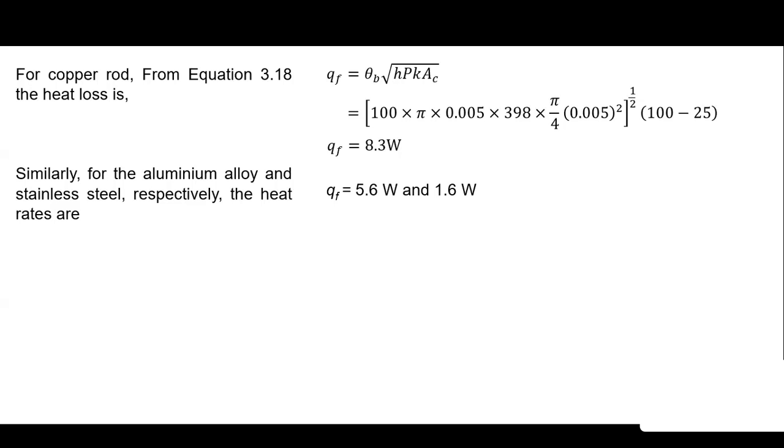Of course, we know that because the thermal conductivity of copper is highest, it is as expected that it will carry a large amount of heat in comparison with the other two materials whose thermal conductivities are less. So we can say out of these three materials, which one is the best suited material for the fin? It is of course copper.